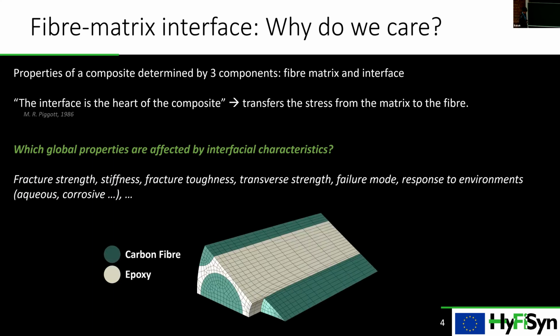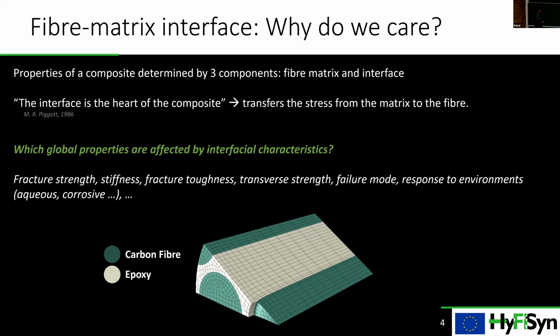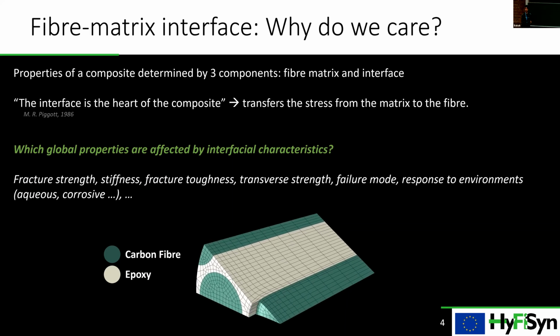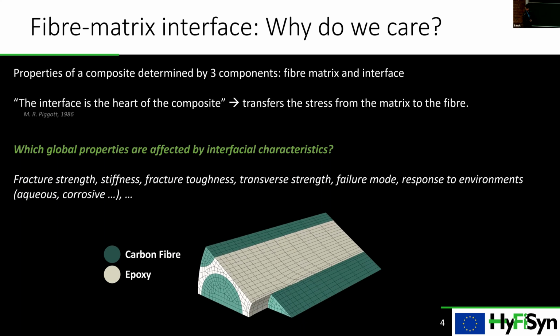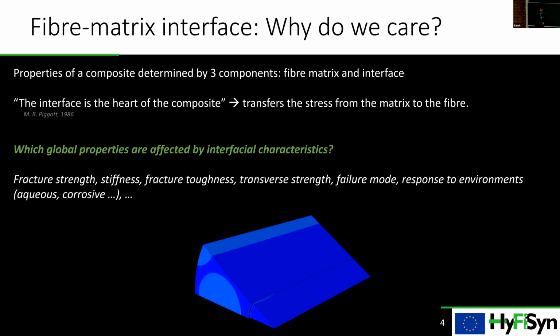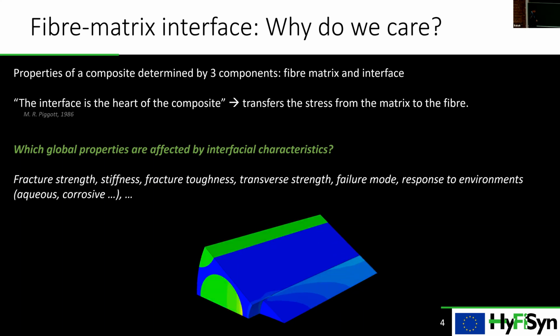But why do we care about this interfacial failure in composites? Well, if we are looking at the bigger picture, we are interested to see how the stress will redistribute itself in the broken fiber in a full composite. And more importantly, how the stress will redistribute on the neighboring intact fibers. So we don't want to overestimate or underestimate the failure strain of the composite, by correctly representing and modeling the interfacial failure.